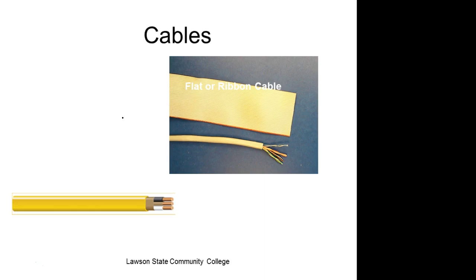Originally, if you go in real old houses, they don't run a ground wire. It's 2 wires, period. So the neutral is supposed to carry current. That ground wire is not supposed to carry current. So if I get any flow in the ground wire, it means that current is going somewhere else, right? You understand? It means you got not only a short, you don't have a ground.